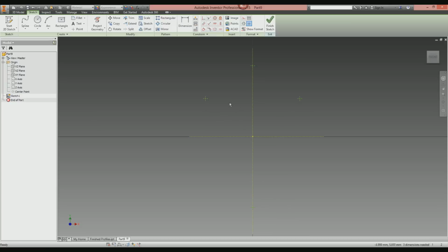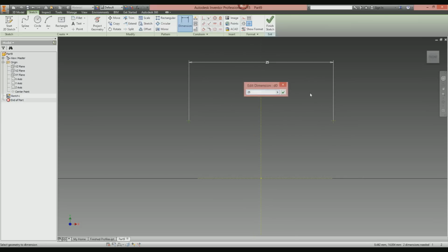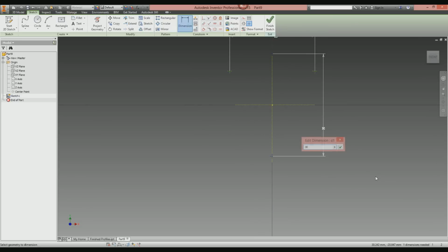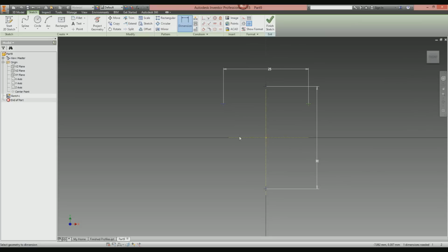The next thing we can do, if you want to, is place some dimensions. Now I'd be quite alright, now that everything's symmetrical, to create a spline between these points, but if you are designing a product, you might want to put some dimensions on at this point so you know what kind of size you're working with. So we can maybe create a dimension from here to here and make this, say 25. You might want to put a dimension from here to here and make that, I don't know, 30. Whatever, it doesn't matter. I'm just making this up as I go along, if I'm honest. And then make that one 10. Now all those sketch points have gone blue. When a sketch line goes blue, I don't want to get into too much depth, but depending on the color scheme you're working with, they can go a different color.